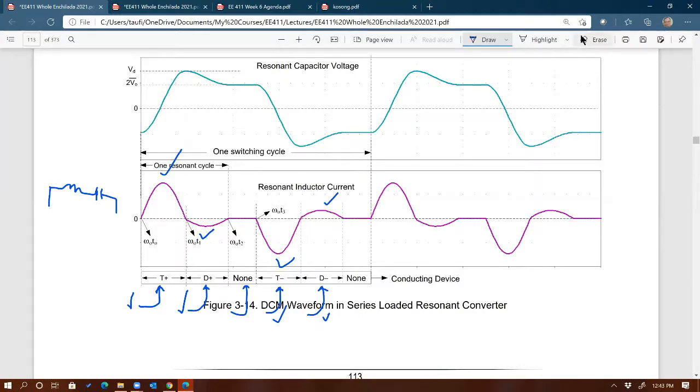And just like I did for the previous soft switching circuits, these waveforms, I didn't draw these waveforms. I got these waveforms from OrCAD PSpice. I simulated the topology, and these are the waveforms that PSpice gave me, right? So I didn't make up these waveforms. This came out of the simulation. Any questions so far? And then we can go over what happens with the circuit, with the waveform, when different devices are conducting. I had a question.